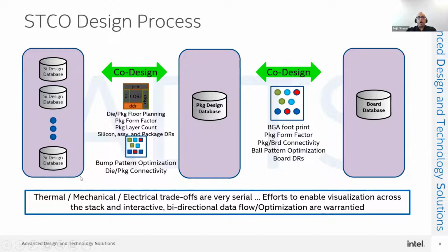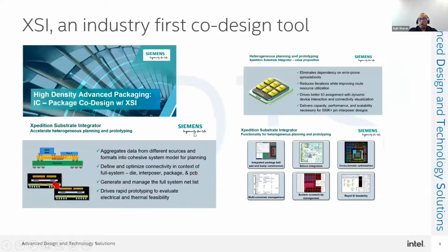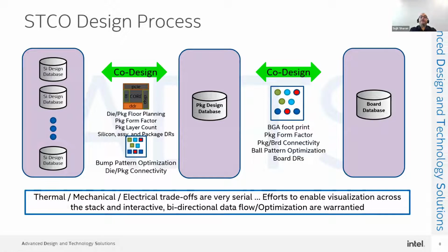So we do a lot of work around how we optimize the IP layout, how we put the bumps there, which is the right location for the IP placement, what the whole floor plan is going to look like, how we are going to break out all of the different power domains, how we are going to break out all the signals, both for die to die, etc. We do the analysis concurrently with the silicon design team. There is still some level of serialism in the system, but at least at the top metal layers, once the silicon database is getting ready, the package engages very heavily, and the board team engages very heavily through the package design team to make sure that the way the silicon is spread out to the balls, all of the signals and power domains are appropriate for the board design that is being considered.